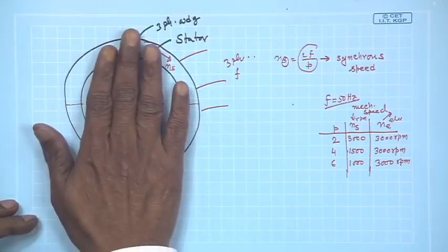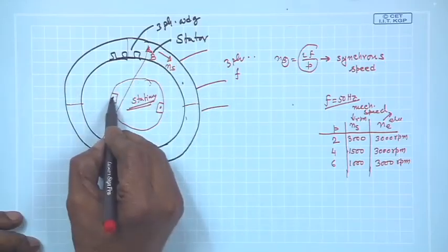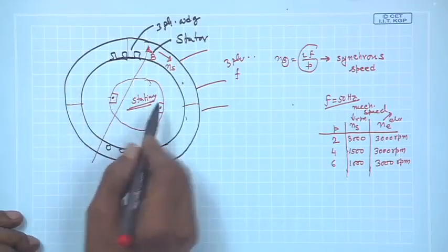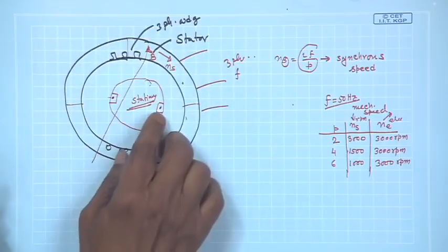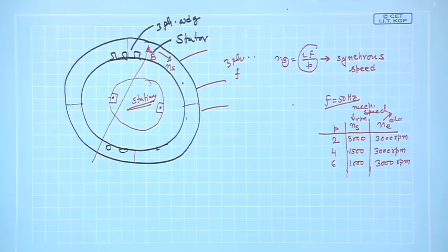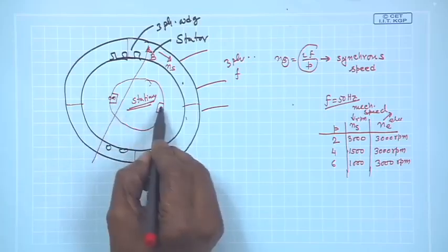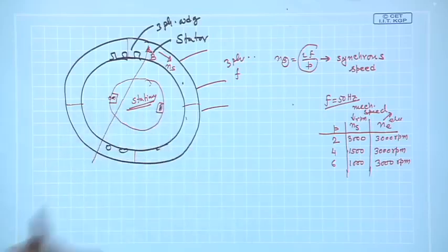Now, as this rotating magnetic field is existing, there is bound to be induced voltage here in the coils, because the flux linkage of each conductor comes under north pole, south pole, BLV is there, all these things we now know. Now, the question is, what will be the magnitude of the voltage I want to calculate in this rotor coils?